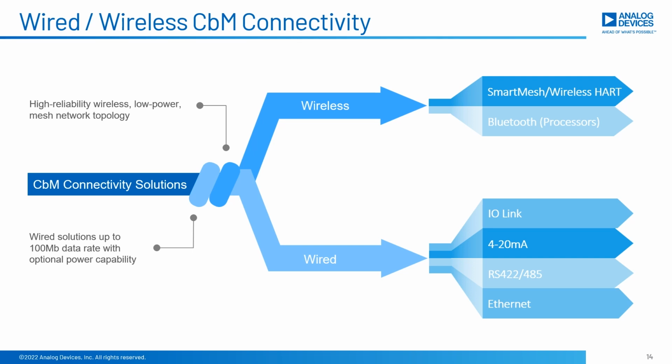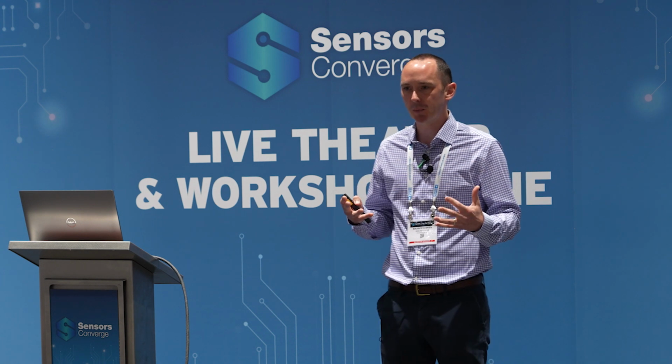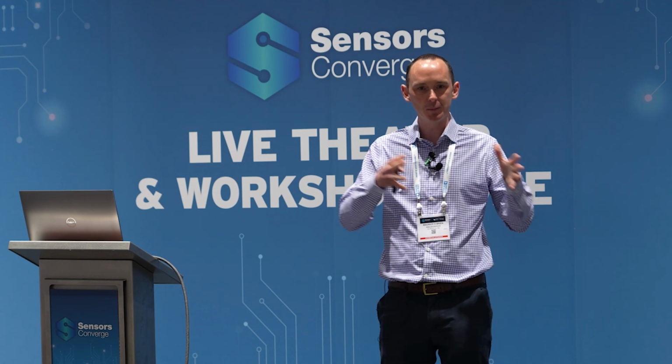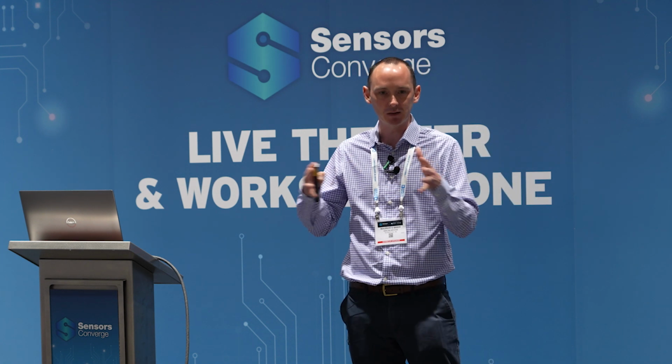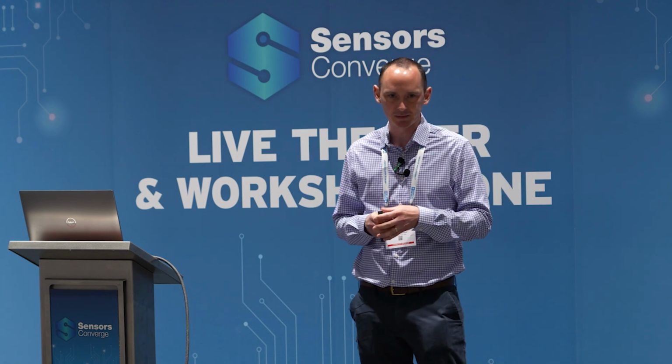And specifically, I'm going to take a moment to look in a little bit more detail at a new industrial Ethernet physical layer called 10BASE-T1L. So Ethernet today in your home requires 4 pairs or 8 wires, and it goes to a distance of 100 meters. If we want to bring Ethernet to industrial, and particularly CBM, we need to use simpler cabling. We need longer distances.